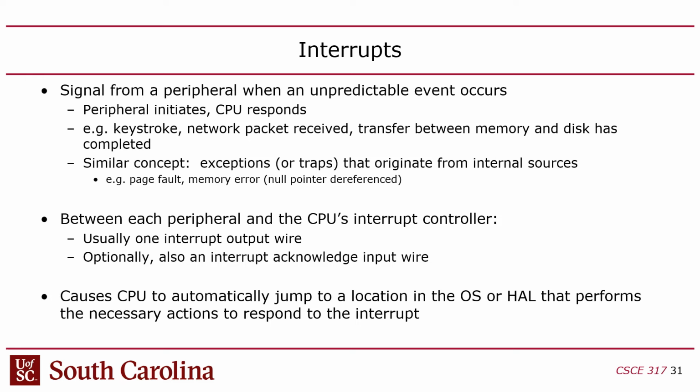So those are interrupts. I think in 313, you guys probably connected the interrupt, for example, from the UART controller back to the CPU when you did it in Platform Designer, but you didn't actually use the interrupt for anything because all the console I/O you do in 313 is just output. But that interrupt that you connected would have been a way, for example, that you could have written a program on the FPGA that said press any key to continue, and you hit a key and it would continue. That interrupt would have signaled that keystroke, right?